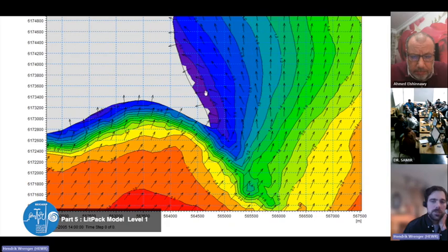So again, if I place a profile here, and I assume these wave conditions out here as the input to my littoral drift, then I will only transform those waves along my profile due to the shallow water effects, so the refraction, shoaling, and breaking. I will not get this change in direction due to the diffraction. There's nothing we could do about it.